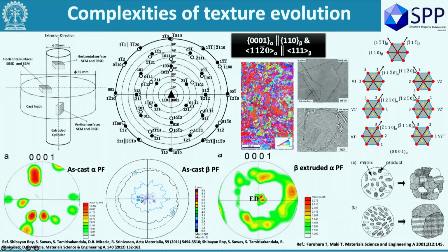You go from here to here, why it is or rather how it is not happening, what is changing and all, I am not going into that. Point is, bottom line is it doesn't happen. This one single thing doesn't really control or explain it. You can do just a simple thermal cycling. You don't need to do an extrusion for this. You simply take this, take it to high temperature and come back, where you started and where you ended will not be the same.